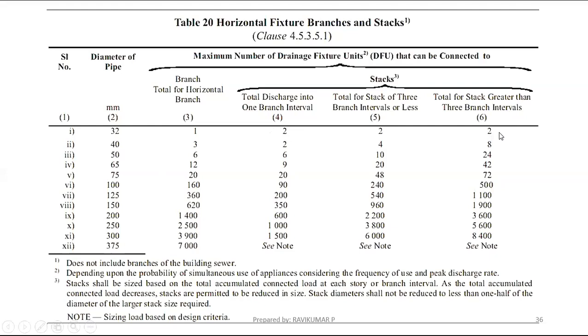So what is the branch interval? Branch interval means floor, the number of floors. How many branches you are connecting into the vertical pipe, that only they have mentioned. So for every floor you are going to connect one branch. So like that you have to think. For every floor, for the vertical pipe, the vertical stack, for each floor you are going to connect one pipe. So that is what you have to get.